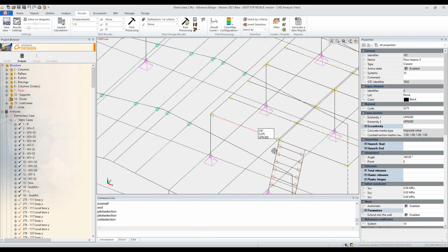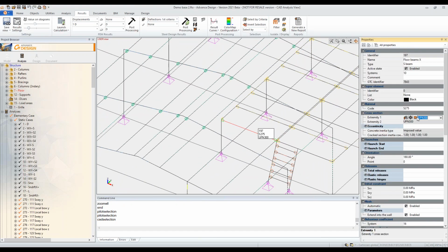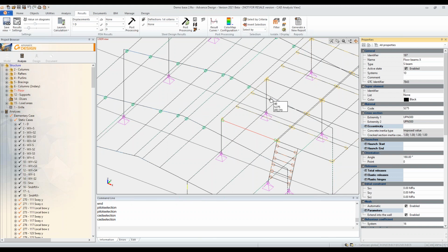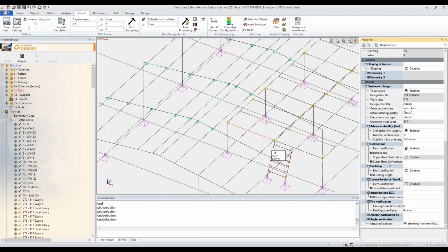and I happen to have a channel there on the platform, you see, this is a channel section. So if you stick by the standard, in this case, you're pretty much on your own, because this section shape is not covered because of the torsion and warping effects. And that's why the advanced stability method we have comes in.